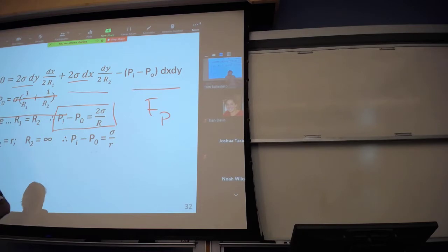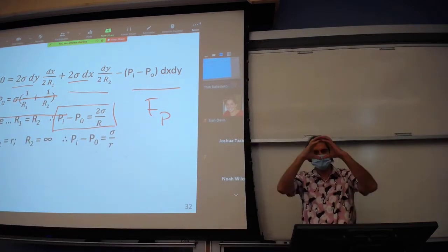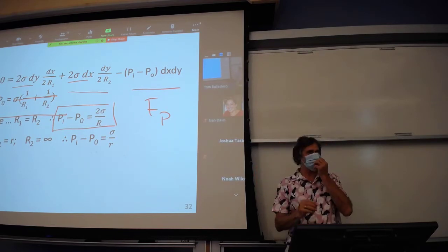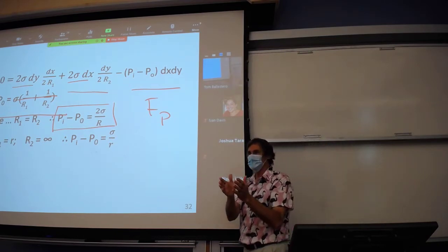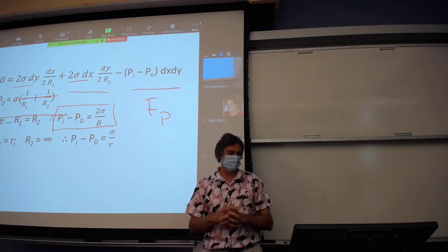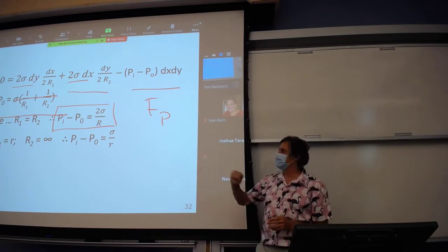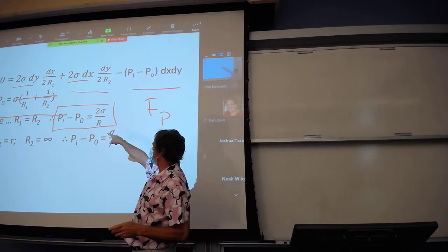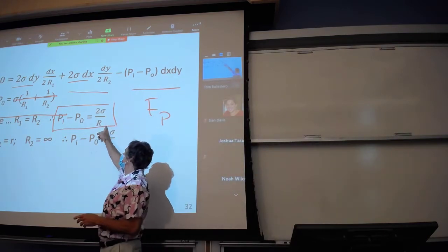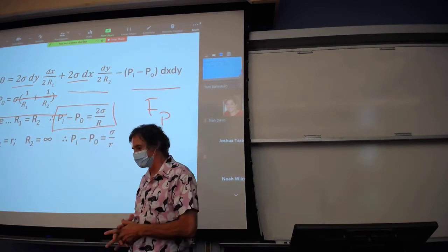And you have to know how wrong you're going to be when you do that. So if we had a sphere, and again, the sphere is the same thing as the test tube, or the same as the capillary tube, that's basically a hemisphere. The equation would be that the difference in pressure across the interface is 2 times the surface tension. And again, we're still using the radius of curvature of the surface. We haven't gotten rid of that yet.